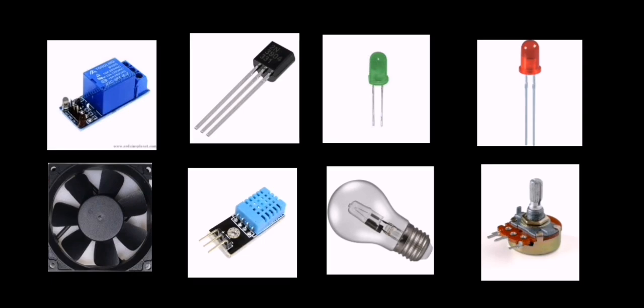The sensor's data pin is connected to digital pin 49 on the Arduino Mega. The sensor's power pin is connected to the Arduino 5V and the ground pin is connected to GND. The setup allows the Arduino to periodically read the temperature and the humidity using the DHT library.